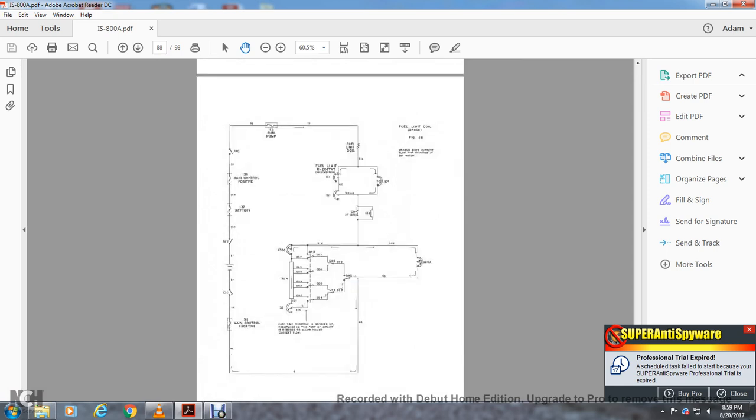Alright, this shows the fuel limiting coil. The fuel limit rheostats 134, 131, 121, and the fuel limit coil. Fuel pump main control positive battery, main control negative. Each throttle notch adds resistance to the circuit, intended to allow the correct fuel flow.